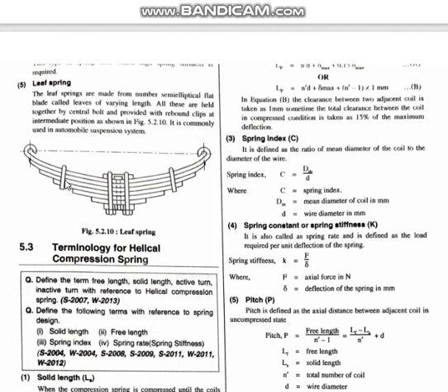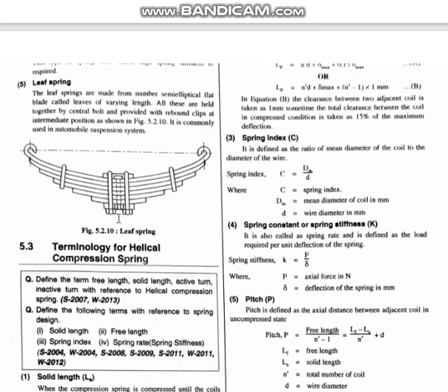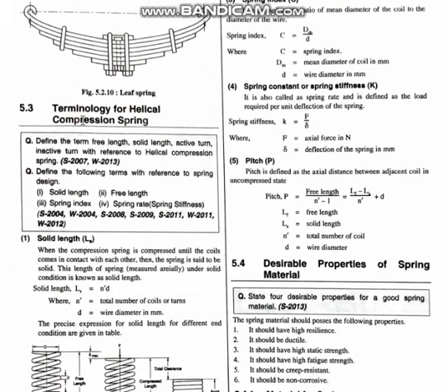These are rebound clips, this one at intermediate positions. It is commonly used in suspension. The top one, which is the full length, is called the master leaf, and the others are called graduated leaves.